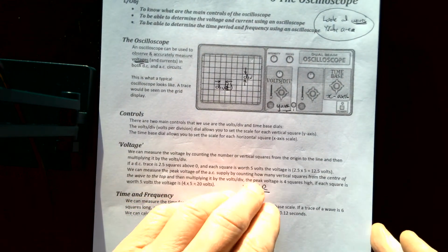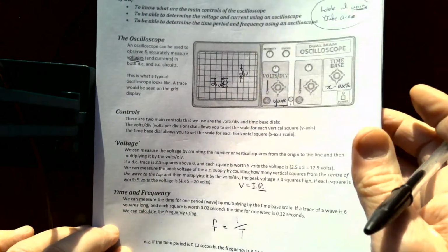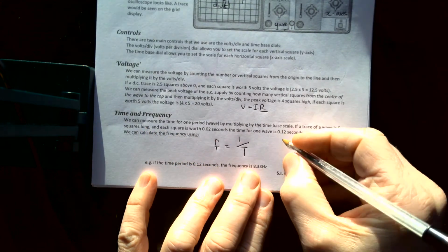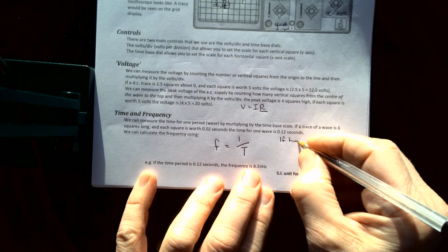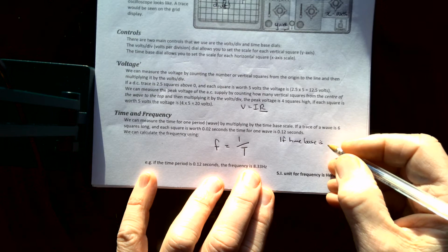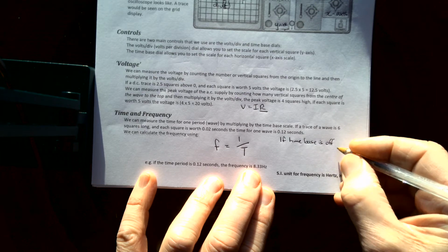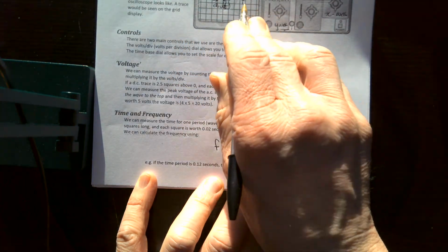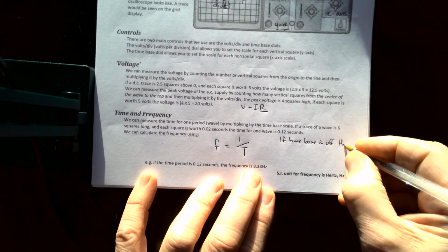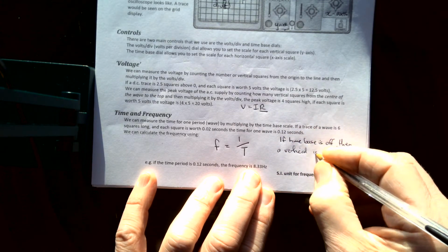Right, okay, so it's probably worth putting in, I don't know if there's space there, no there isn't, so I'm just going to squeeze in at the edge that you can actually turn off the time base. So if the time base is off, and you often use this in investigations because it's really handy, if you've got a wave or a changing pattern, it's a bit easier to do this. If you turn it off, then you get no time going sideways. The dot stays on its spot, but the voltage is moving it up and down. Then a vertical line is displayed.